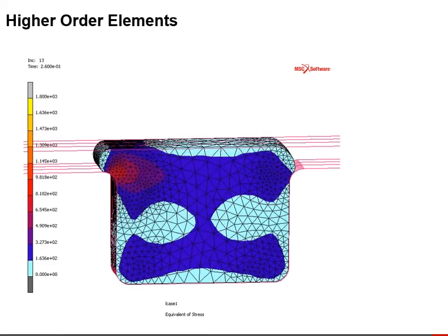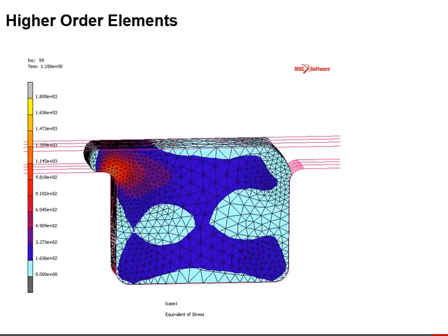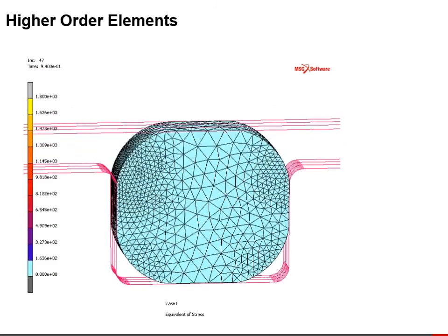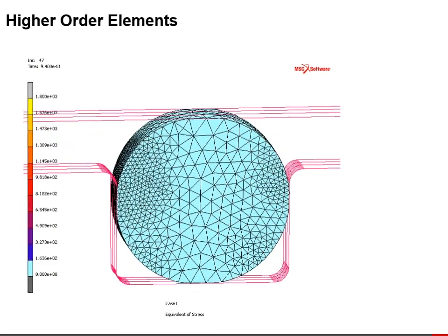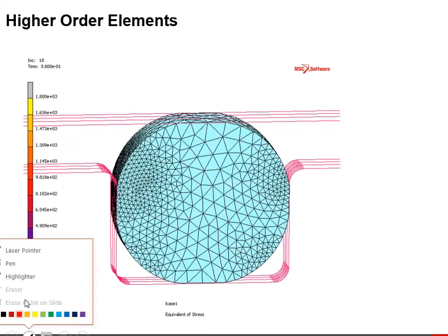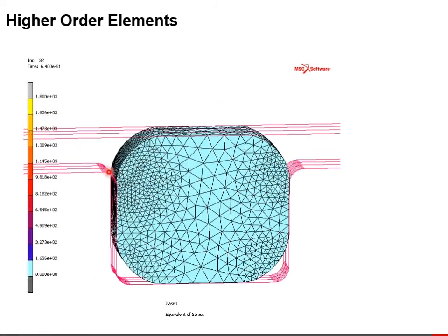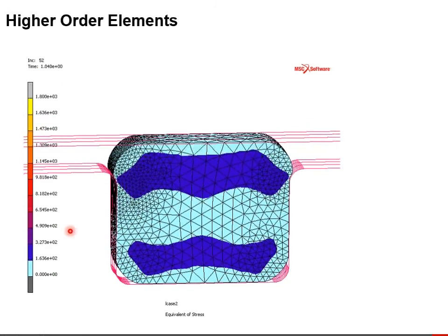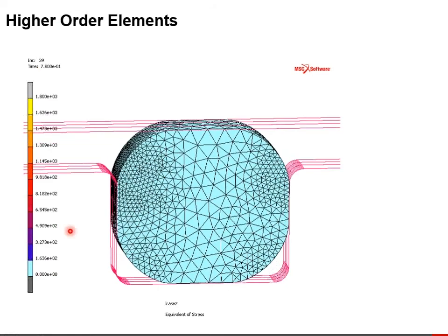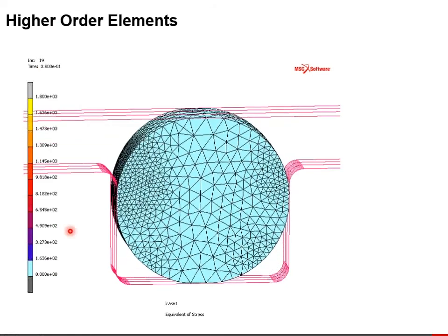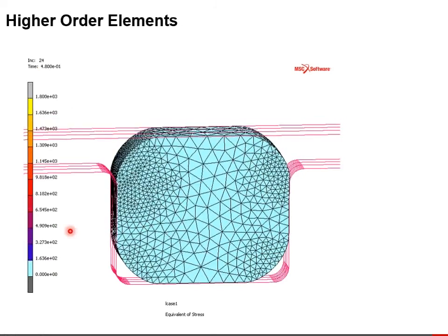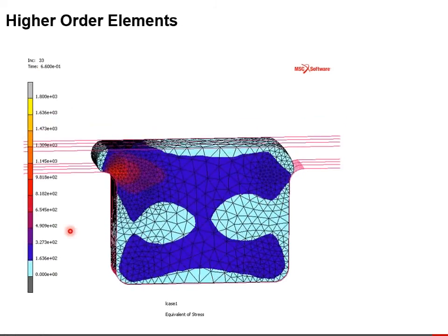It's a typical gasket type problem, and this is done with rubber. And because effectively this curved region over here, using the higher order elements, we can much better capture that geometry. And a simulation like this actually runs further using higher order elements than using lower order elements.